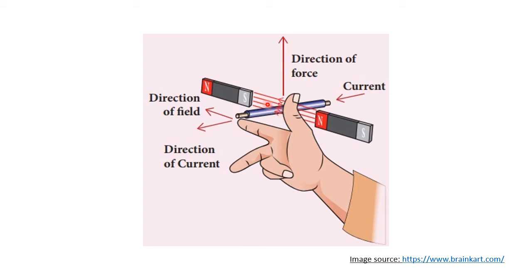Okay, so here three directions are there: the magnetic field direction and two more perpendicular directions. If the conductor is moving in one direction, the motion and the magnetic field should be perpendicular to each other. Then for these two, there is one more perpendicular direction, along which the induced current will develop. That is indicated by the right hand middle finger. Once again, the magnetic field direction is indicated by the forefinger and the motion of the conductor by the thumb. Then inside the conductor, the induced current will develop in the direction of the middle finger of the right hand.